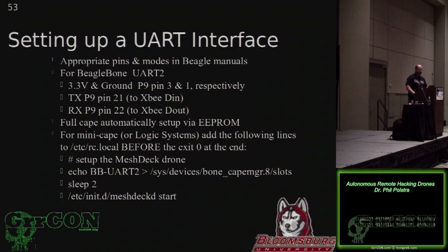And by the way, this might be cape_manager.9, depending on the version of the software you're running. And you put this into an rc.local file, and it will just start up that routine to run and listen for commands. But before it does that, it'll say, hey, by the way, I wanted to use these pins. So please set it up as this UART.